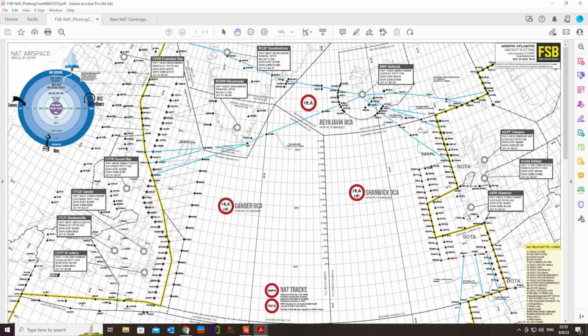There were some cases that aircraft crossed those routes without any HF communication. If you have a CPDLC, you can do that also with CPDLC without having to check in on an HF communication. But you need clearance for that.